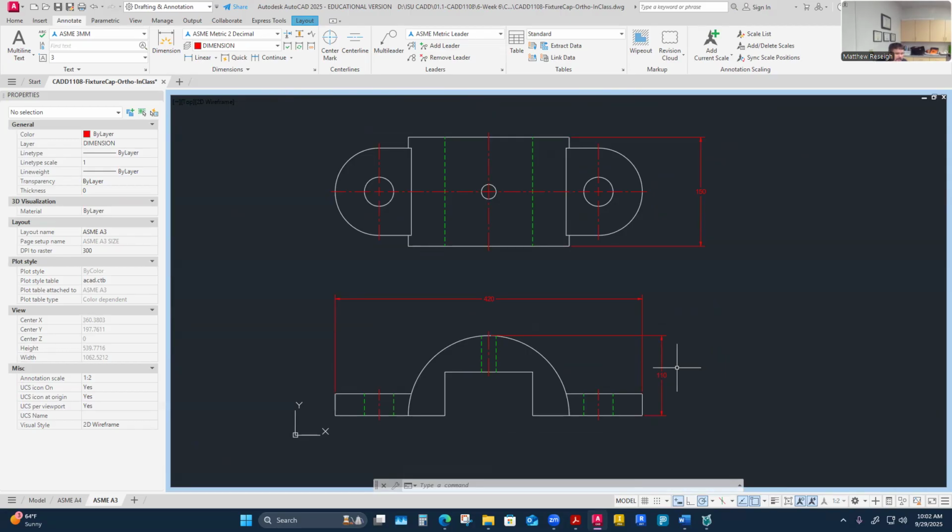Now I break this down into features of the part and their size and location. I do holes kind of last, and I look at the features now as follows. It could be all one uniform part, yes, but I can view the ears as separate from the cylindrical shape feature. So I have ear features with holes in them, yes, but just the ears themselves, their overall shape. And then I also have a cylinder and its overall shape. And then I have this inner bore, this cut, as a feature and its overall shape. So I work systematically, thinking of size and location.